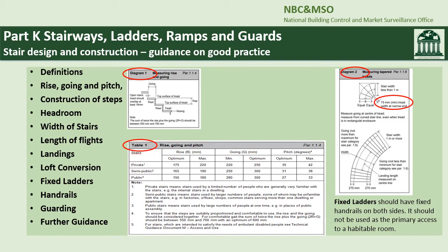Construction of stairs notes the use of tapered steps in certain situations, and the mechanism for measuring these are illustrated in diagram 2. Tapered stairs and winders are not appropriate for public stairs. Where winders are used, they should be used at the base of stairs.